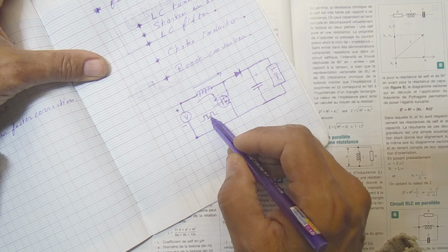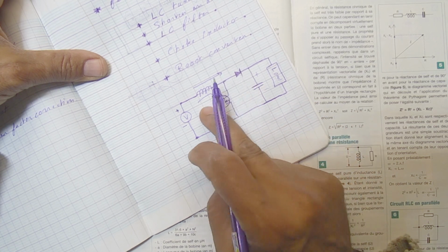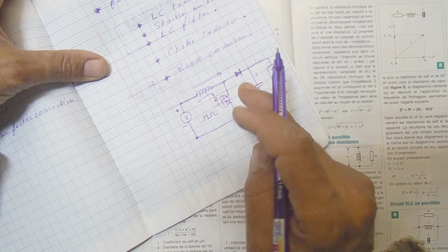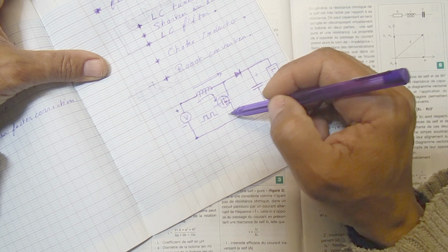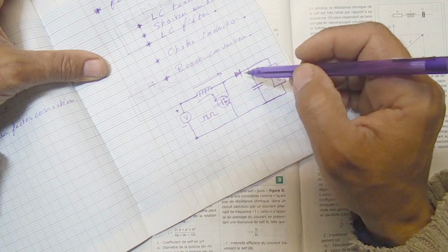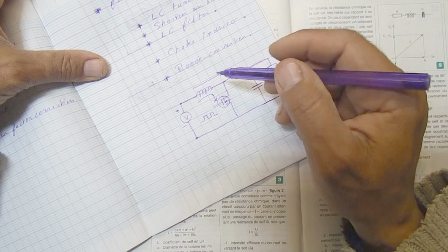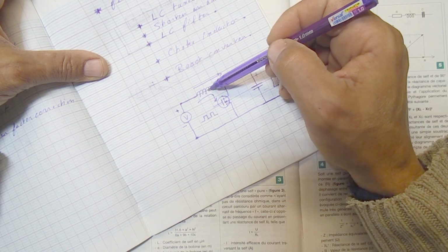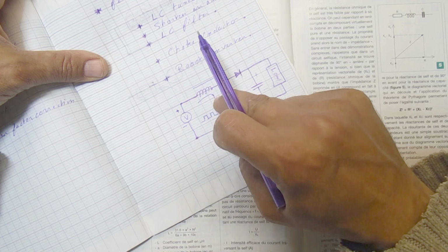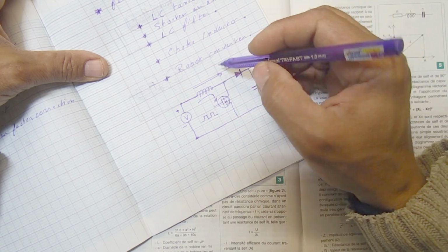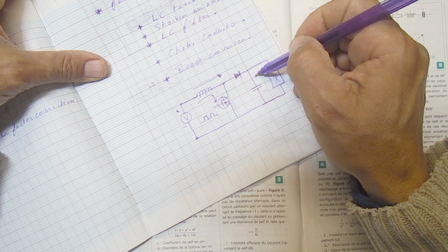We can adjust the voltage here by adjusting the pulse width. We have pulse width modulation here. Of course, here we can find the microcontroller that controls the MOSFET, and we can use a feedback to adjust the voltage here. Because every inductor, when the current passes, will store the energy, and when we stop this current, it will try to maintain this current and will charge the capacitor.